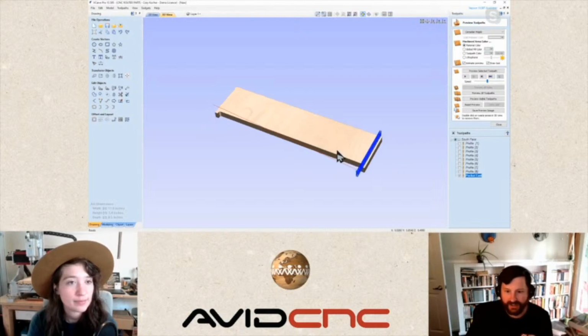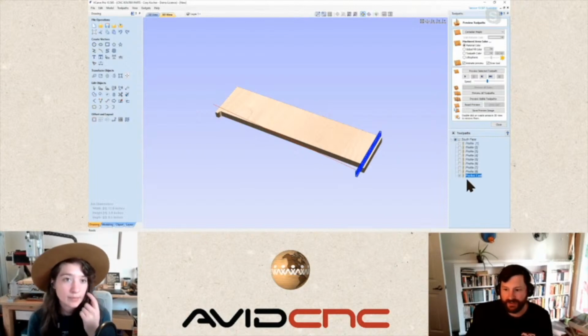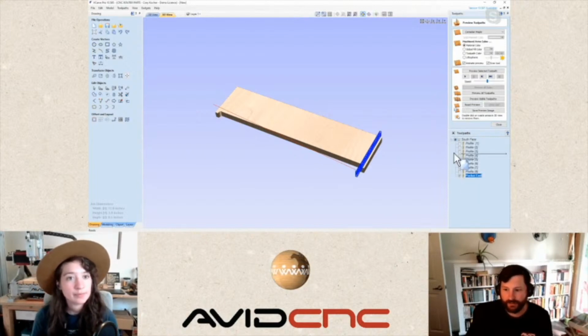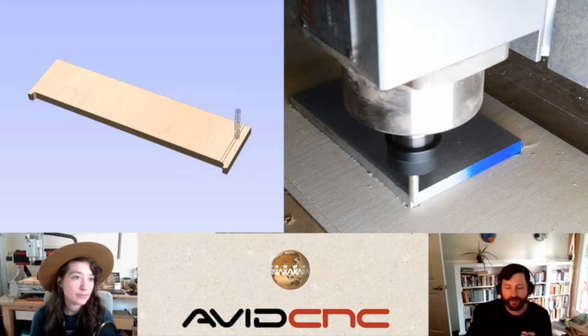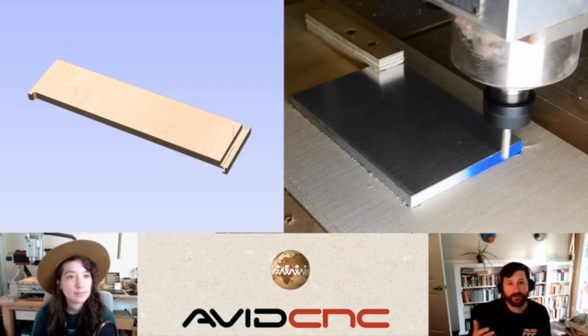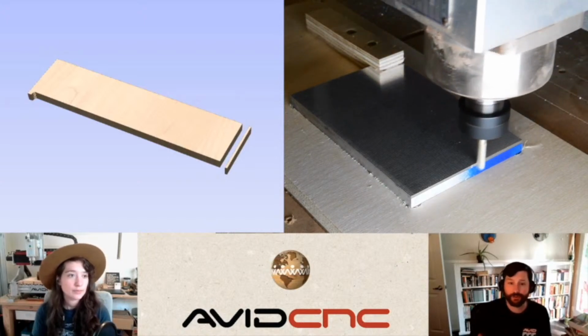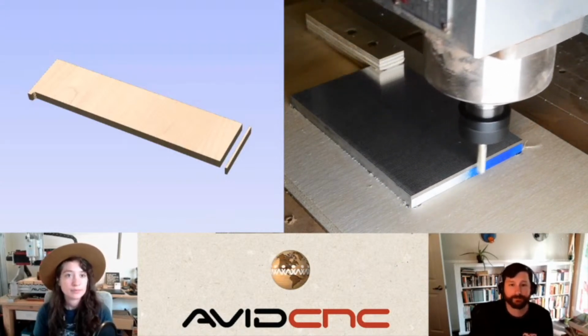And so you can see here we are going down, and we will be at cut depth when we engage in our north travel. Let's go ahead and move this into its own toolpath area and preview that. Again, what we're focusing on here is making sure we have great chip evacuation and making sure that when we are coming back along our finished edge, we don't have full tool engagement. We're only engaged in that climb cut.